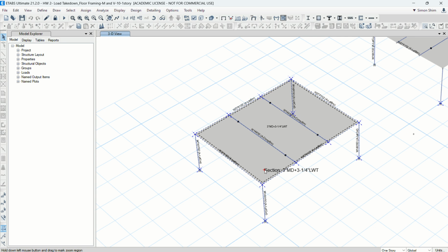So this beam is part of a rigid connection, right? You see that negative moment. Well, this one doesn't have a negative moment. You see the only single curvature moment diagram, right? Because I release the moment, right?